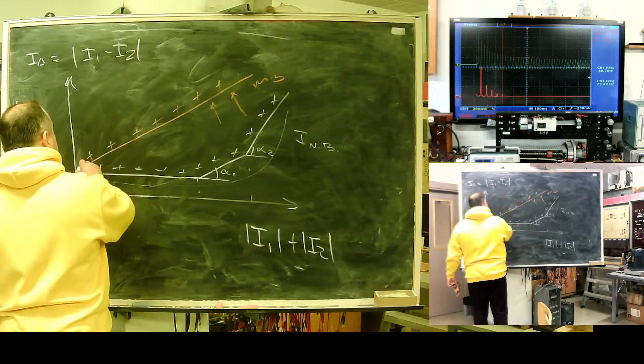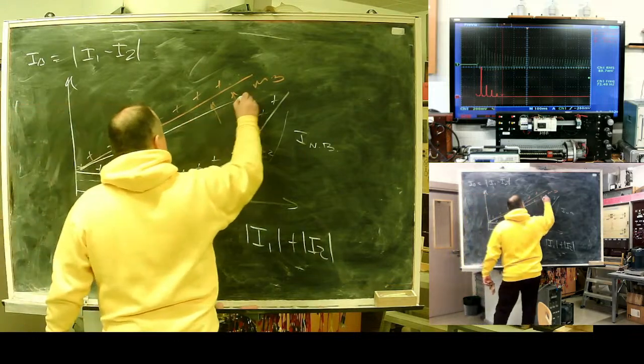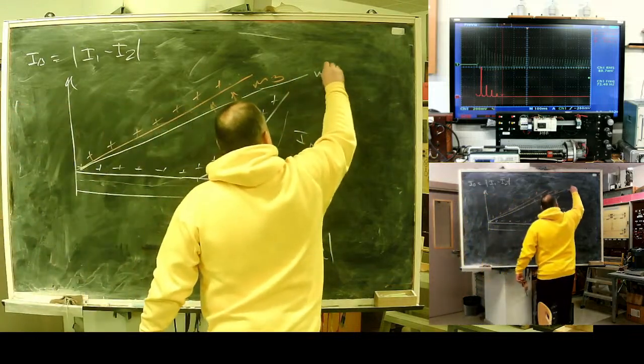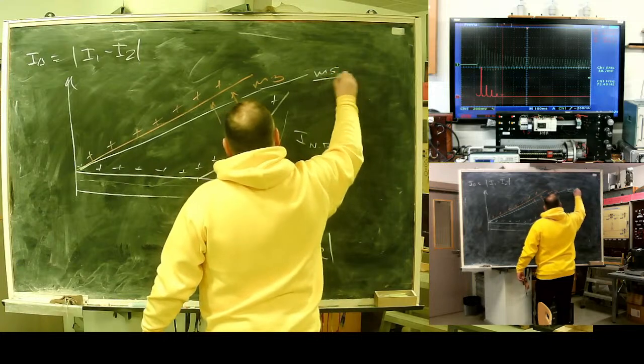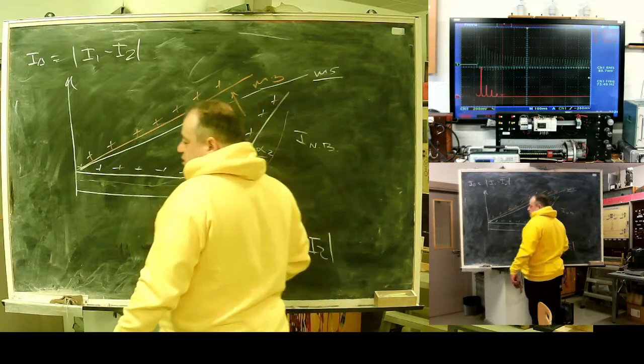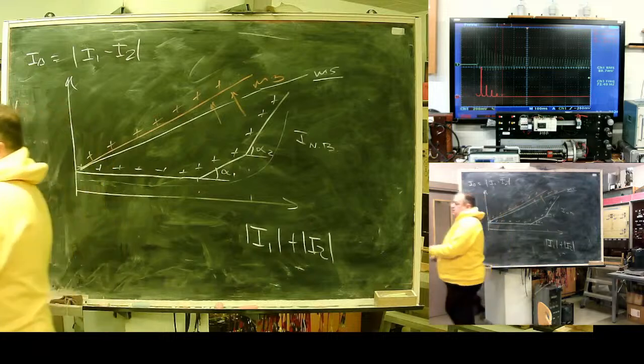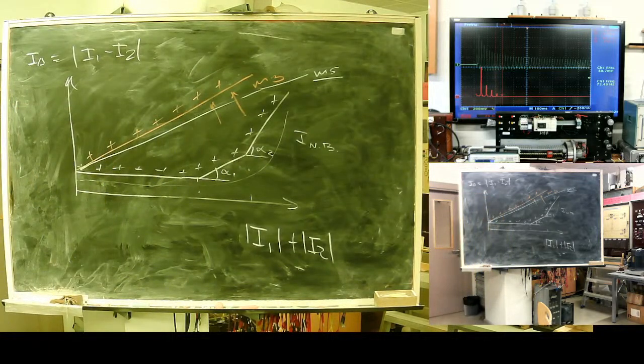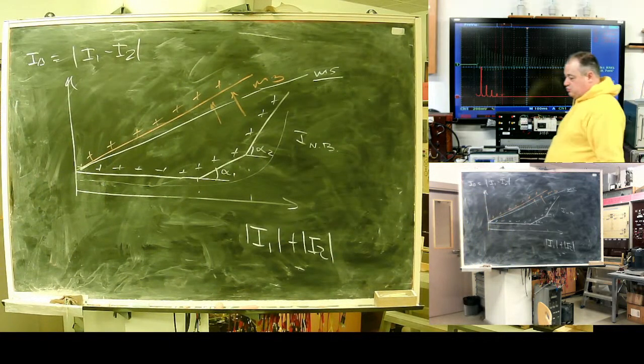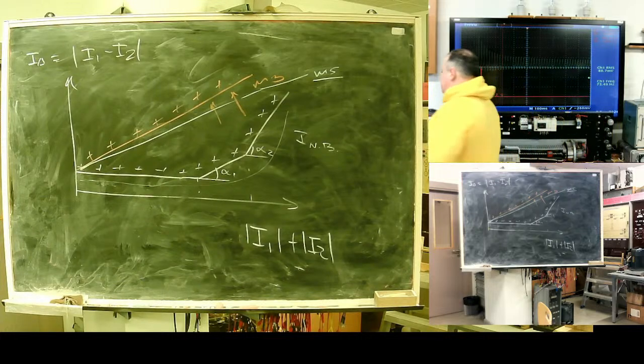Maybe if you really need the fifth harmonic, for saturation of the measurement transformer, a restricted characteristic should also be imposed.